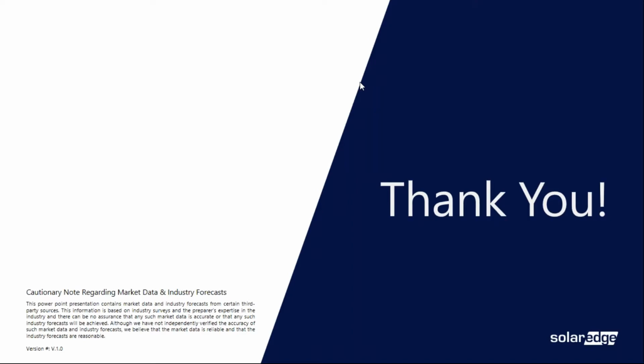So the question is, my company sells a lot of Tesla Powerwalls. How does this new SolarEdge technology integrate with the Tesla Gateway? That's a great question. So Energy Hub with the Tesla Gateway still is going to work great, because not only does it have a production meter, it has an import-export meter, which, if you have a special requirement like zero export or something like that, means you don't have another box or another meter to install.